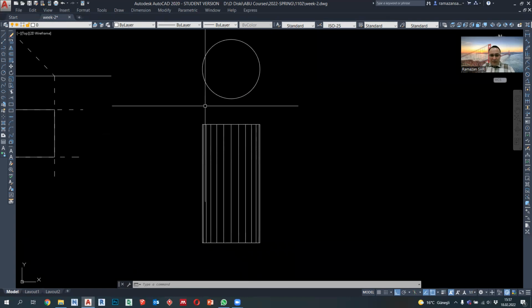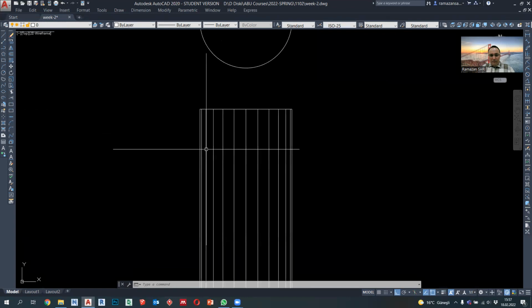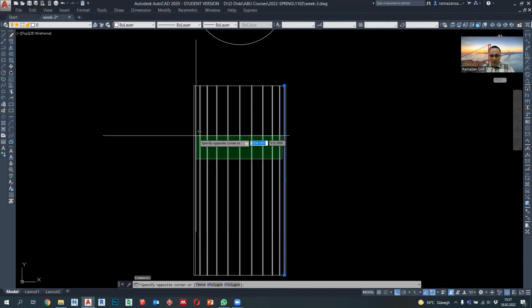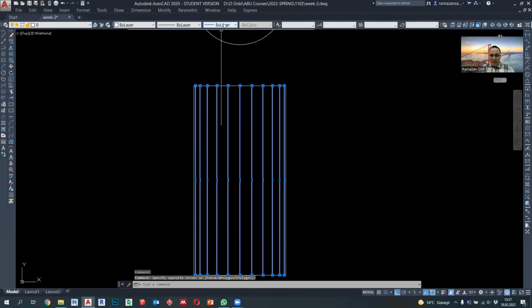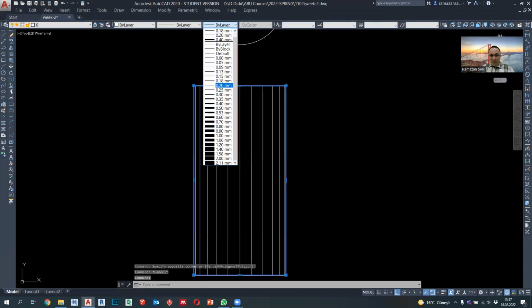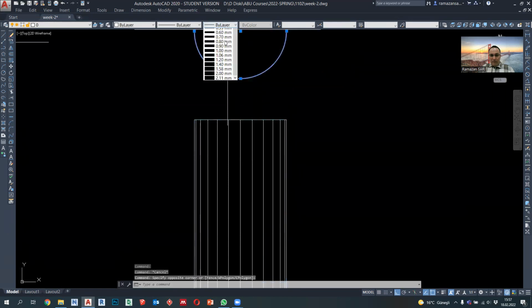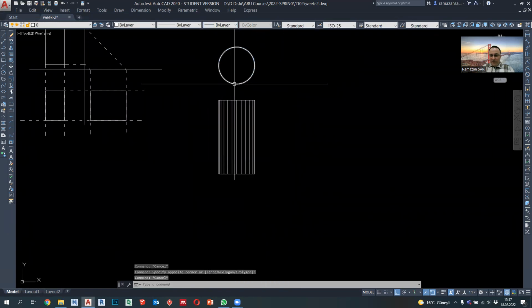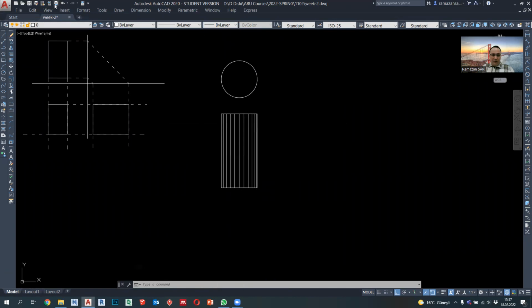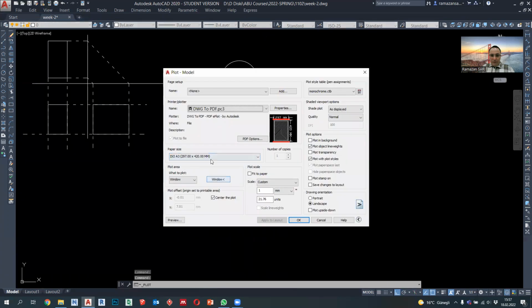So we said that all the lines specifying the texture of a surface must be done with thin line, always thin line, and the border of the object must be either medium or thick line. Okay, so separate the surface hatching from border of the object. Okay, let's check our object.